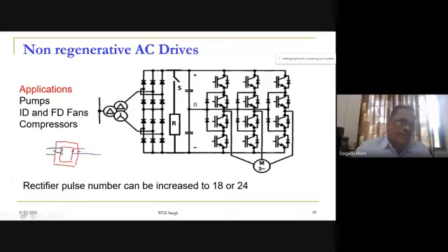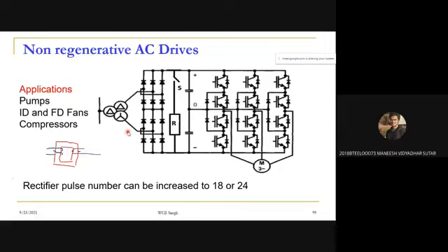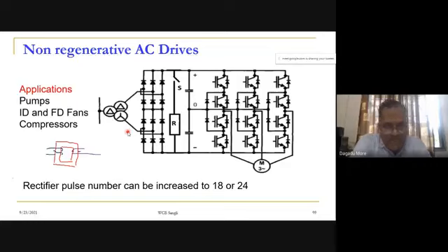So here, we are having a 3-phase, 3 winding transformer. How many primaries will be there? 2 primary or 1 primary? 1 primary, and 2 secondary. A transformer can be fed from only 1 winding, so we have only 1 primary and the number of secondaries may be any number.